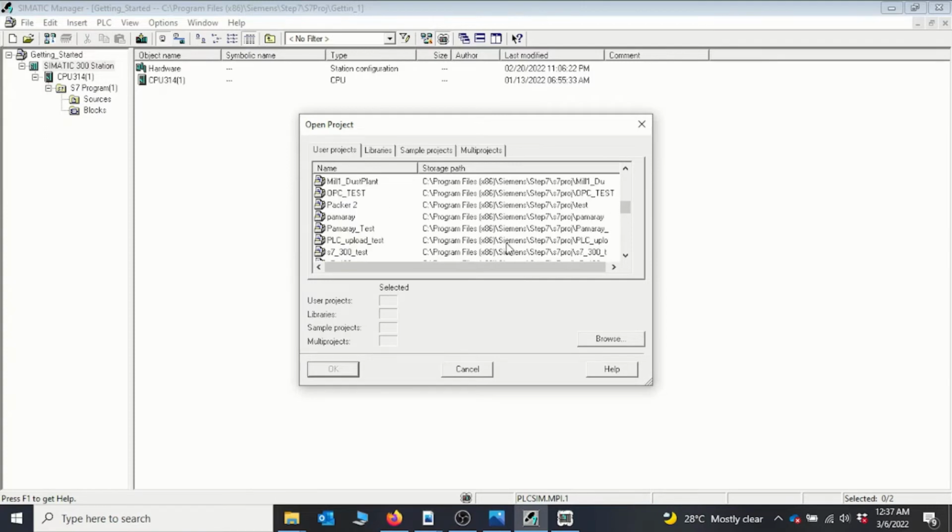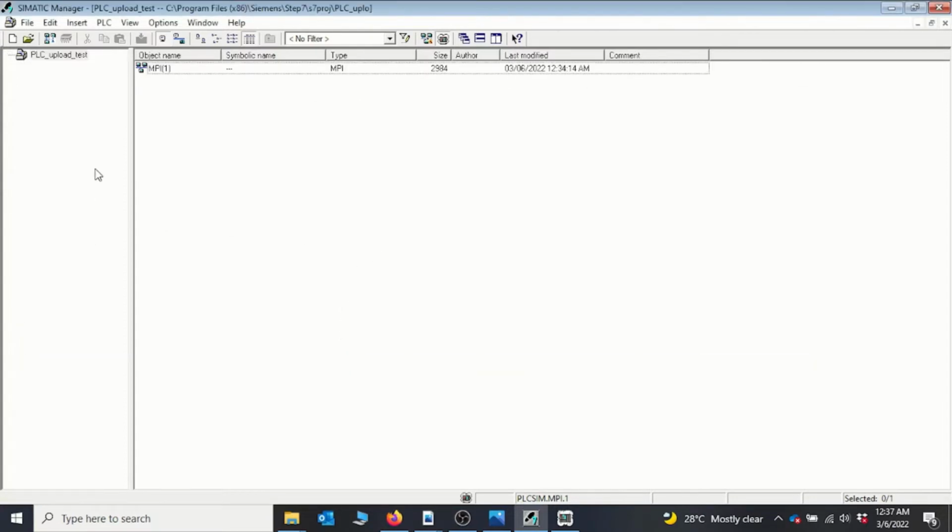I'll look through for the PLC upload test, and I say okay. I can see that the PLC upload test that we just created is right here. Now the idea is that we are going to upload the program from the PLC into this new project that we've just created.